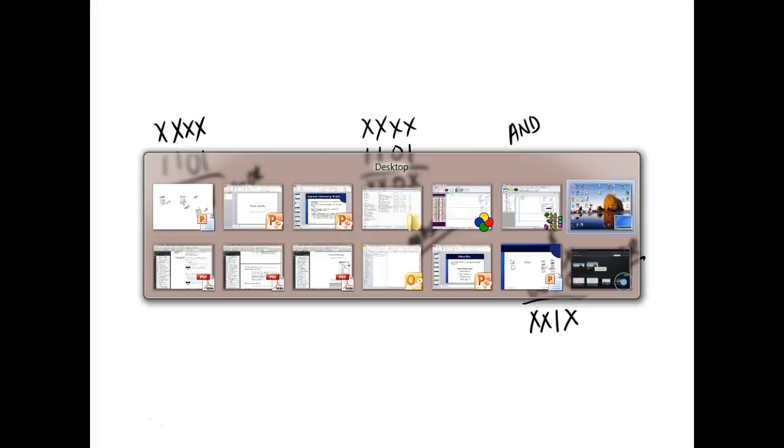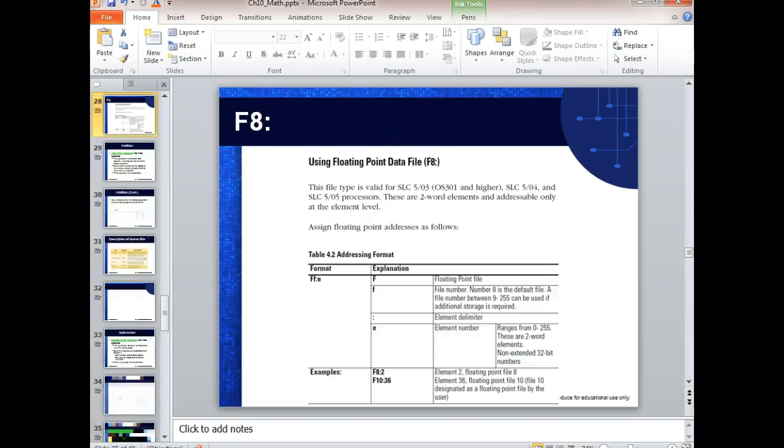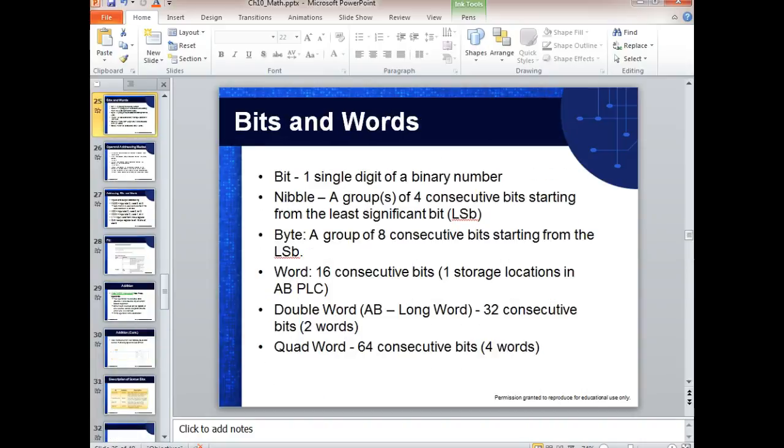So what would we use the overflow for? I don't see anything we would use that for. I mean, I'm sure, because when is the overflow set? Overflow is set normally when the sign of the number changes. We exceed the range of our numbers. Okay? So if I add two positive numbers together, I should get a positive answer.